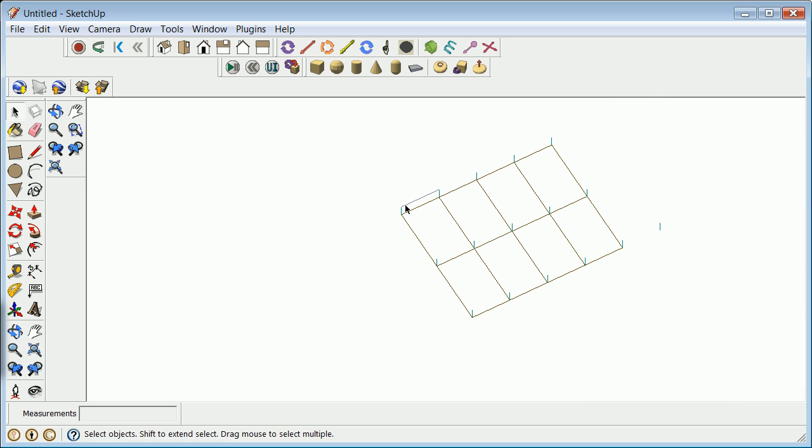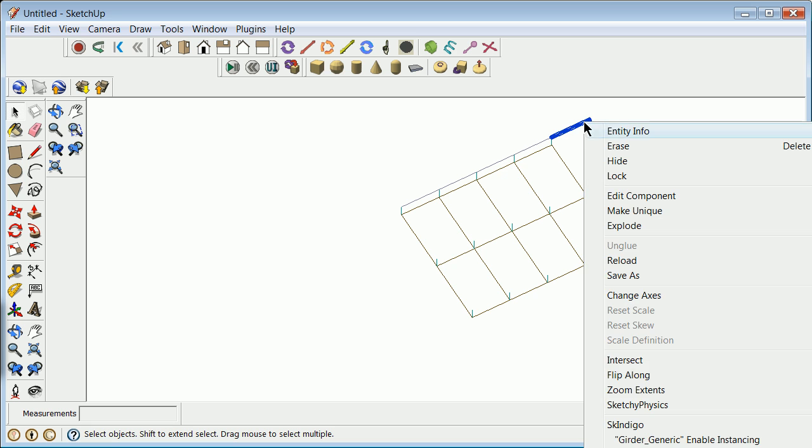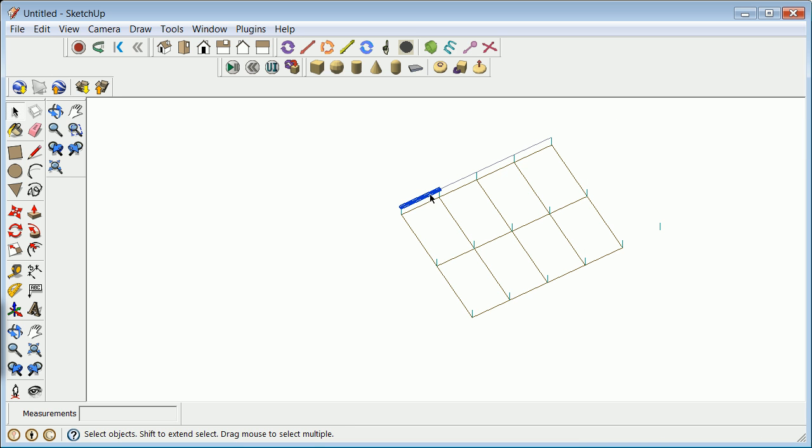Now I can take this here and once again hit the control key there 4 times. I guess I don't need the 4th one, but I'm going to go ahead and erase that. I'm clicking, right click, erasing. I'm going to grab each of these. My hope is that they're on the girder layer. And I can once again now take and hit the control, the copy key, come to there. I go to kind of find along here. I want to go 50 feet and then 2 times.